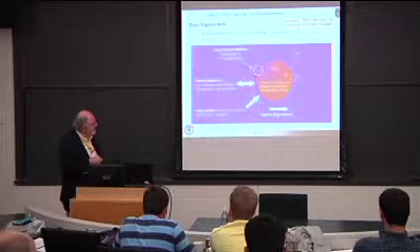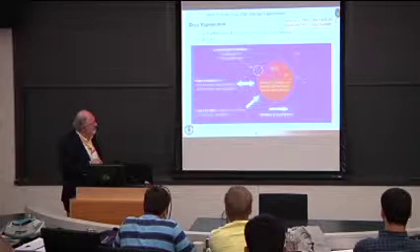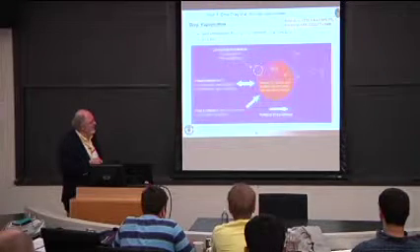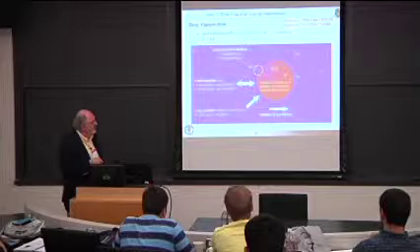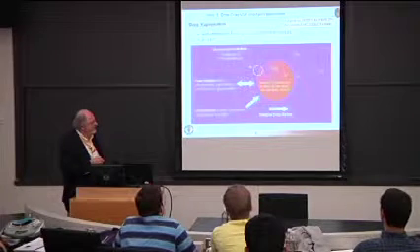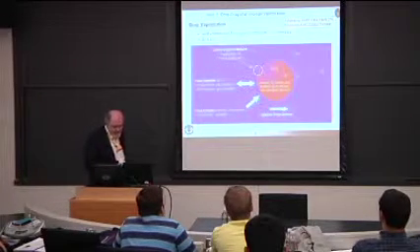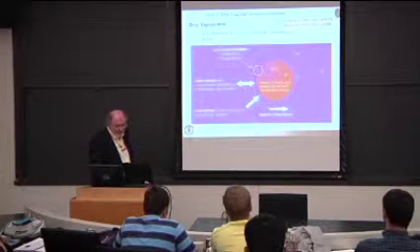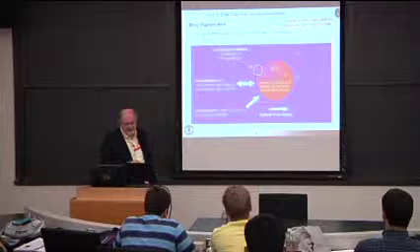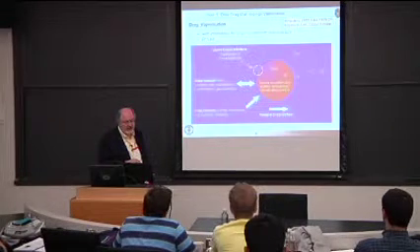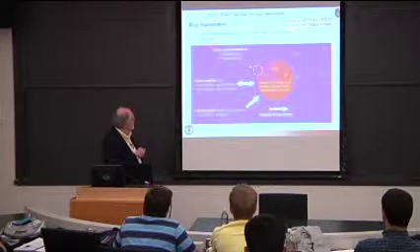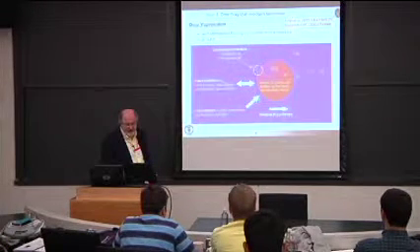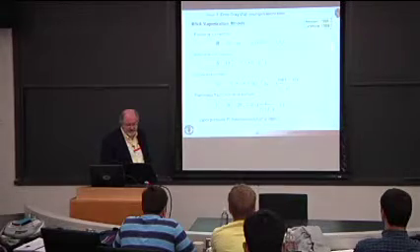Just for reference here, this just shows distance away from the surface of the drop, the mass fraction, say, of the fuel, and a temperature profile associated with high temperature ambient and the surface of the drop. Okay, so all of that has to be somehow included in a model. For single component, low pressure environment, we are familiar with the so-called D-squared law, was mentioned by somebody, which describes the droplet vaporization process very well.